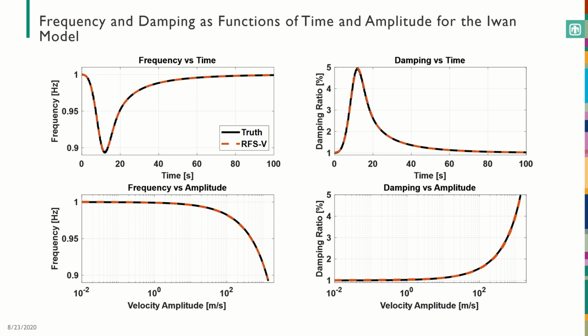The actual least squares fit was done on segments of the response about 2 seconds long, with an overlap of 90%, and I fit 2 term polynomials to C and K in each time segment. These lines are what come from averaging all the overlapping portions together. You can see that they overlay almost exactly with the truth solution that we have for the I1 model. Nice.